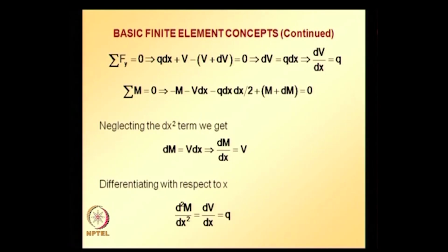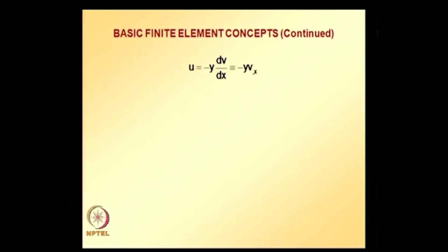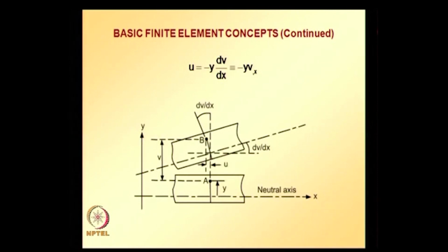So we need a relation between moments and transverse displacements, and moments can be related to transverse displacements by considering the beam deformation shown here. It is assumed that the transverse displacement v is small, and plane sections remain plane after bending.